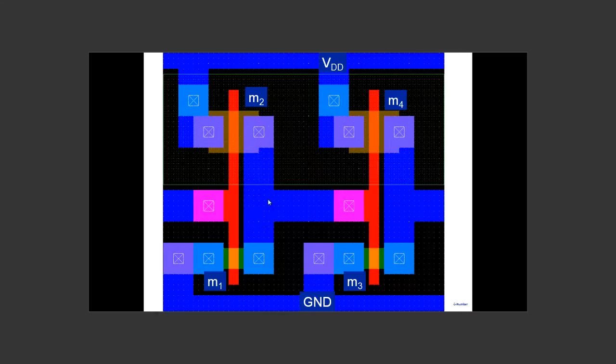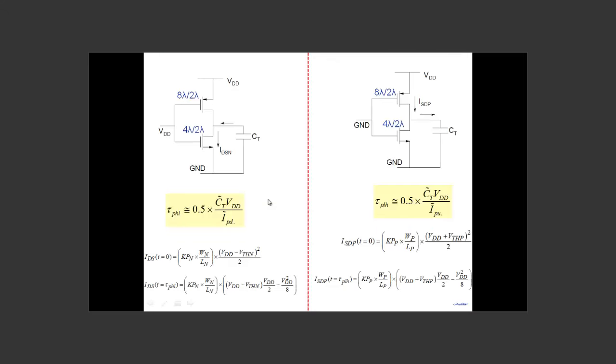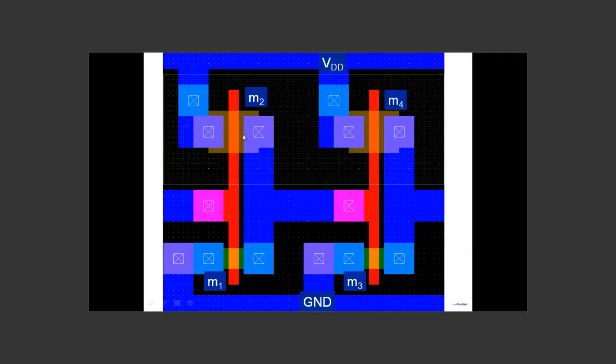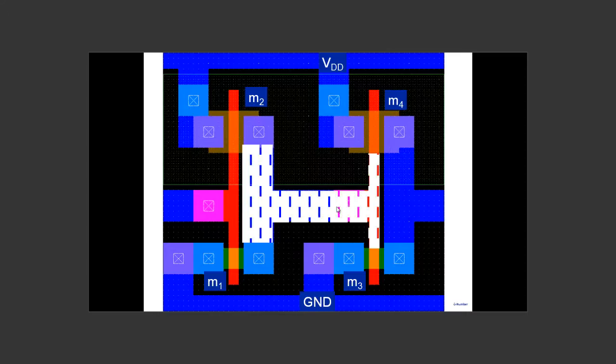So if you want to do more accurate analysis, if you go back to the CT here, we need to add an additional capacitance, which is the interconnect capacitance. This metal is used to interconnect one inverter to the next, so interconnect capacitance will also come. Because we have put the two inverters right next to each other, adjacent to each other, the interconnect is not very large. So there's not going to be too much error. But if this inverter had been far from this particular inverter, then the wire capacitance, we've discussed this earlier, would have been more significant here.